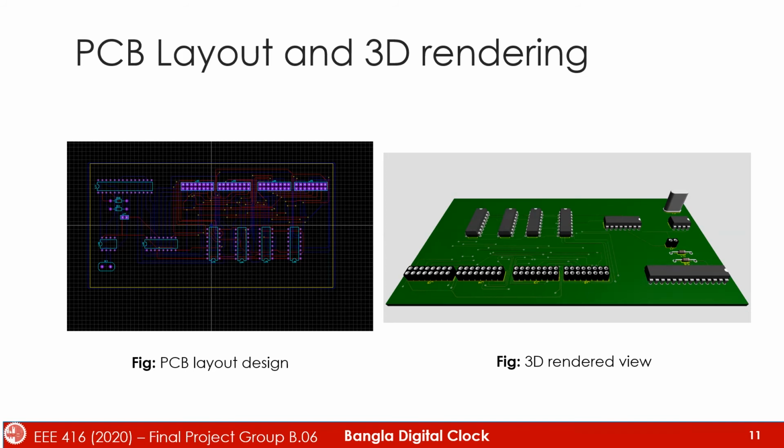Now I will demonstrate the PCB layout design of our circuit, which we have built using Proteus 8.10. For the PCB design, we need to have inputs and outputs, and so we have added a 2-port connector to include VCC and ground in our circuit. We shall be incorporating the external dot LEDs with this PCB layout. So for those dot LEDs, we have included an adequate number of connectors.